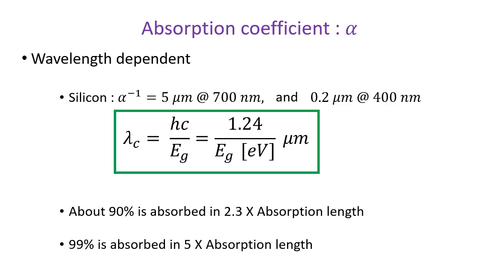smaller. So you see, this is a typical characteristic of these photon detectors, where there is a long wavelength cutoff. That would mean that if you associate an energy which is smaller than that, then one will not register that as a signal. So for example, I've obtained this expression between lambda c, which is the long wavelength cutoff, and the band gap in a semiconductor detector.